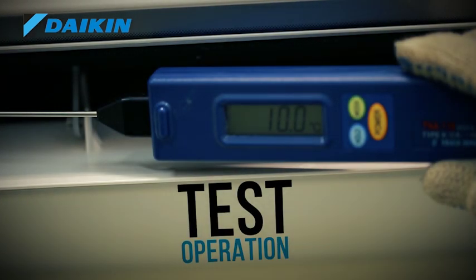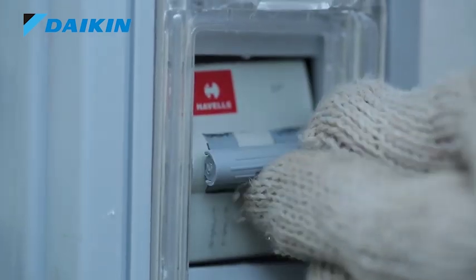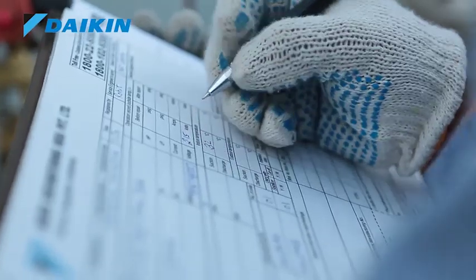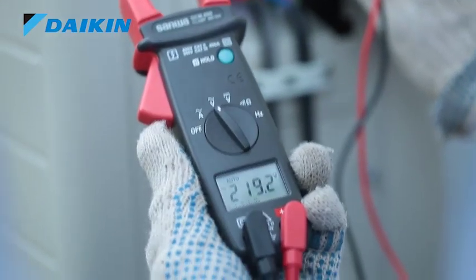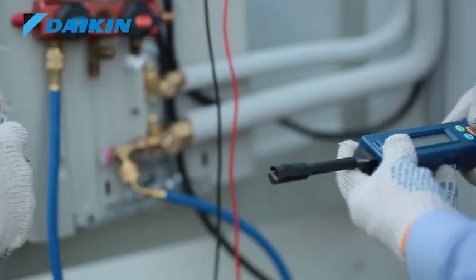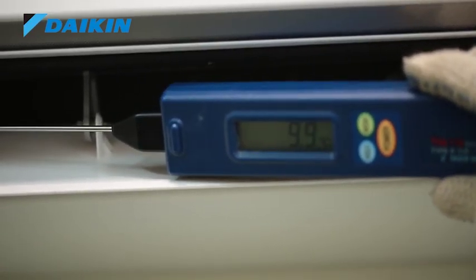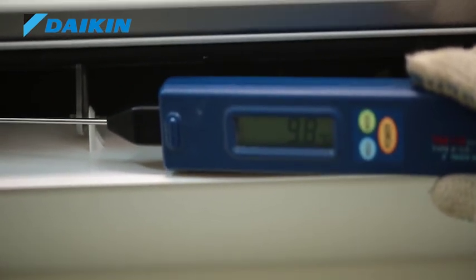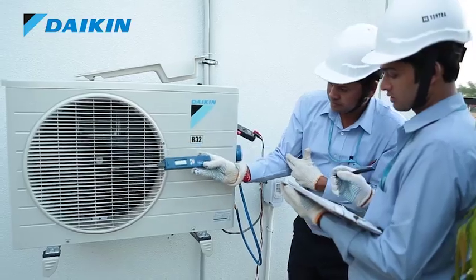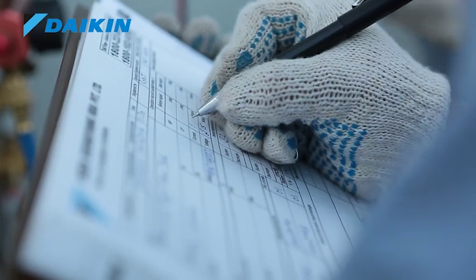Test operation. Now, switch on the main power and operate the unit. Note down the basic operational parameters like input voltage, operating current, suction pressure, suction pipe temperature, suction and discharge air temperature at indoor unit, suction and discharge air temperature at outdoor unit. Fill all these parameters in the commissioning report.